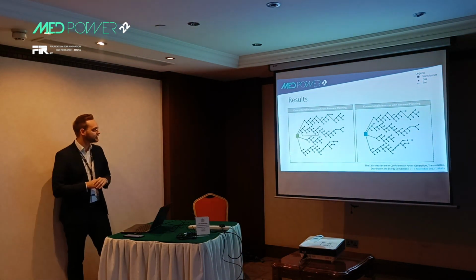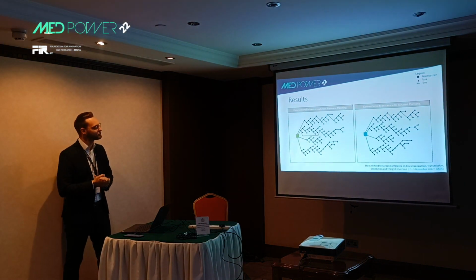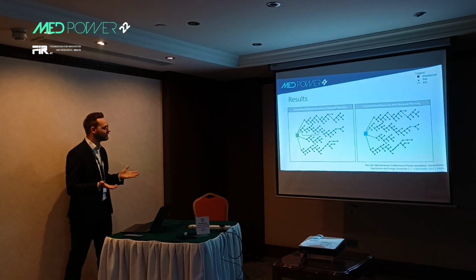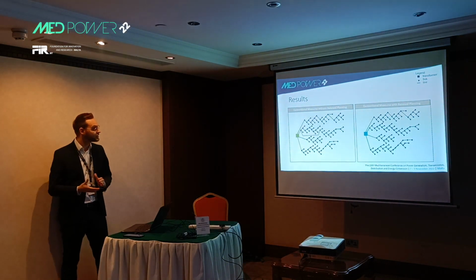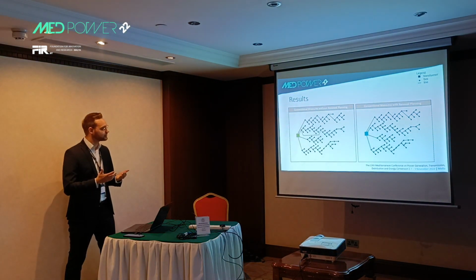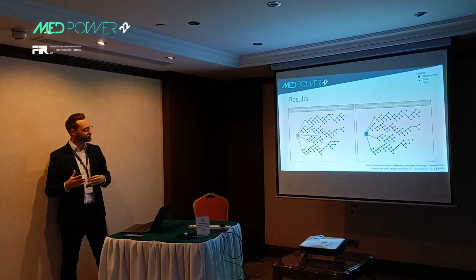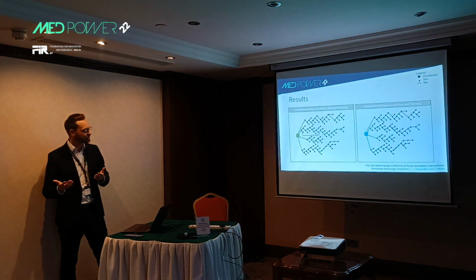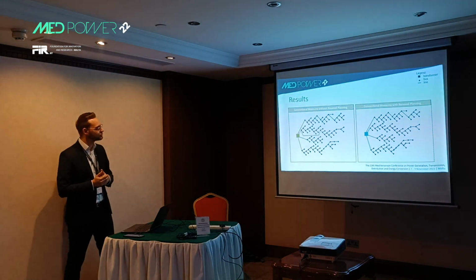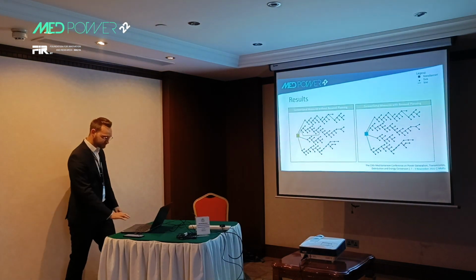On the left side, we can see the conventional measures without our renewal planning, and on the right side, with renewal planning. The colored lines and blocks are the planning measures. We can see on the left side, we need to construct a new line in our second feeder, and on the right side, because the renewal planning has changed some power lines, we only need to renew some lines and don't build a new line.